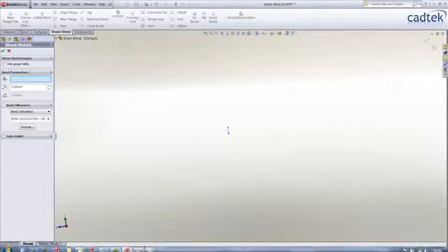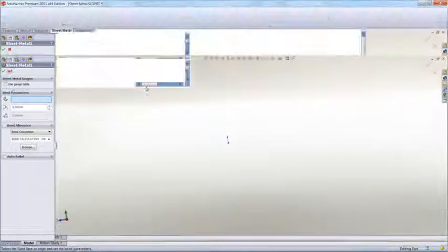Now this is actually an Excel spreadsheet, and what we can see in here is that it gives us a value based on the actual angle of our bend. We can see the bends between 0 to 90, 90 to 180, etc. And anything other than that, it will convert to a common K factor. So let's actually just go ahead and apply this.